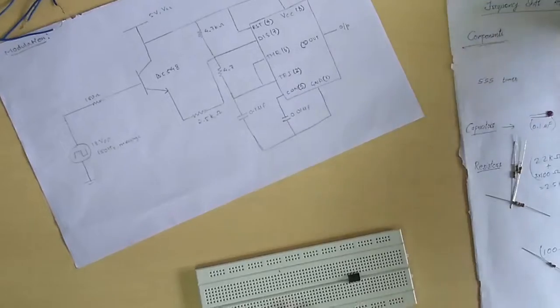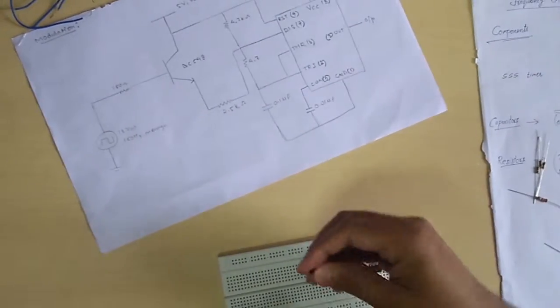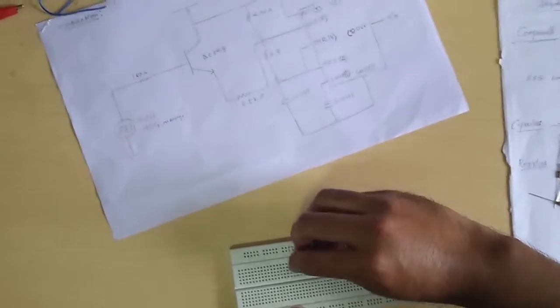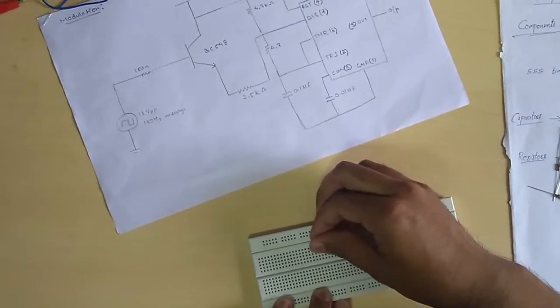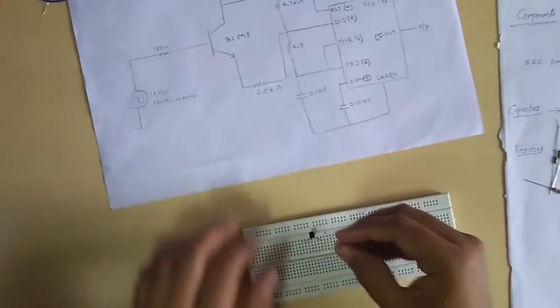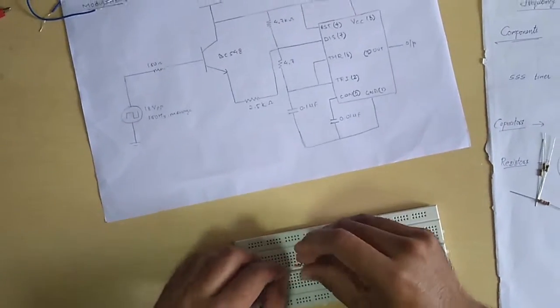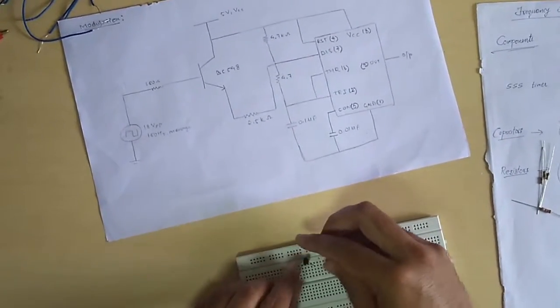I'm going to put it here, and then I'm going to take the transistor from the flat side. Let's connect the base and emitter. So let's get the base part done. This is a 100 ohm resistor that we need from the base, from which we're going to give the input pulse signal to our circuit.